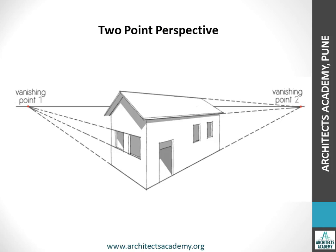This is showing you another example of a two-point perspective where you have two vanishing points, and this is a sort of a house. This is the type of drawing which an architect could make, like a building. In this particular case, you will see that all these lines which are horizontal in actual reality are going to vanish towards the vanishing point, whereas all vertical lines remain vertical. They don't vanish towards any vanishing point. So this is called a two-point perspective.